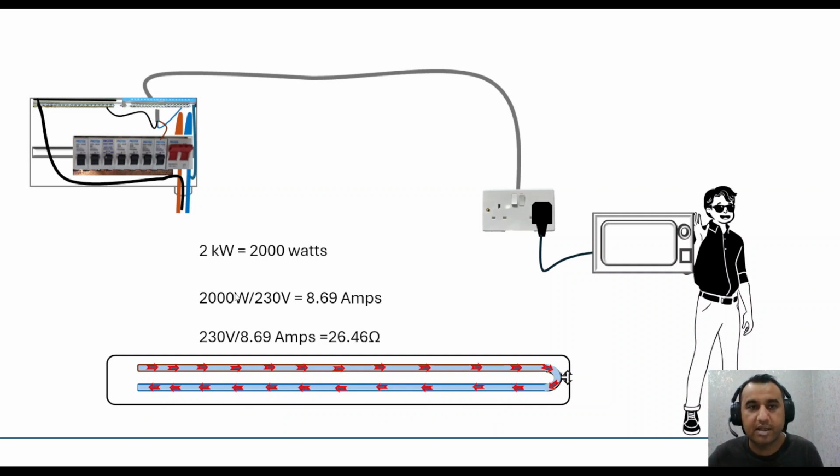In electrics we have the circuit protective conductor. It's probably showing black on the screen. As I said, there's something wrong with the system, but this is what it is. I just put it down in the pipe. So there are two pipes there, and the third one is another shield on top. This is what the circuit protective conductor is going to do. If there's any leak in the neutral or line side, that's going to feed back to the system, depending on how many amps go through this circuit protective conductor, and it will trigger this MCB.